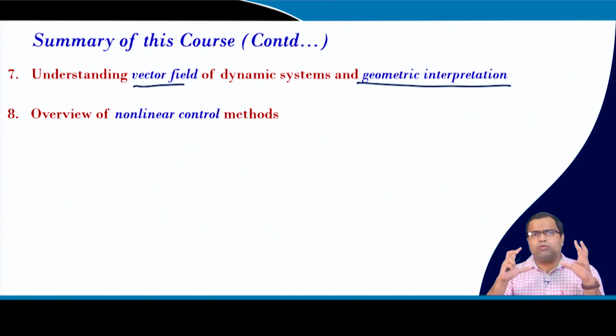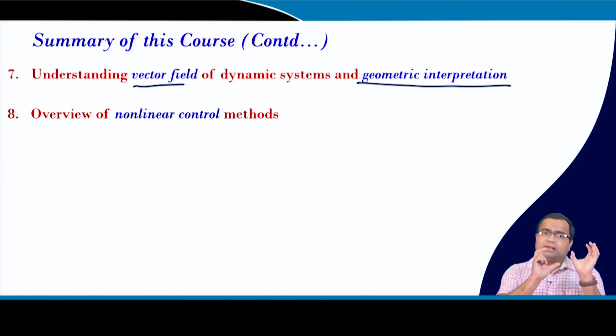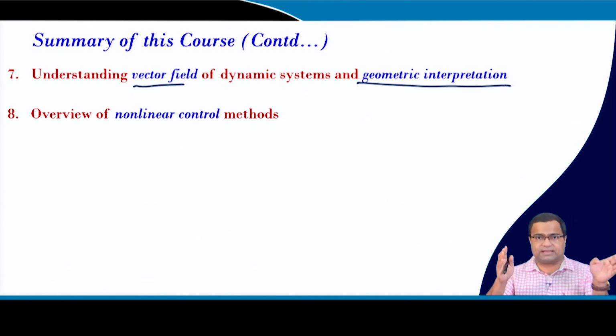Then we saw how to apply the gain scheduling technique in order to take the full advantage. So, gain scheduling is nothing short of a tuning approach, online tuning, where we need to update the controller parameters as and when the operating point changes, because then the location of poles and zeros of the transfer function may get affected, and we need to update the controller parameters, so that we can get optimal or at least better performance than the conventional design based on offline criteria, in which we generally consider the worst case scenario, design the compensator based on worst case, and then plug in the controller value at the very beginning.